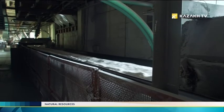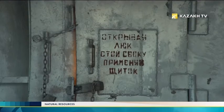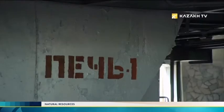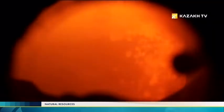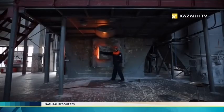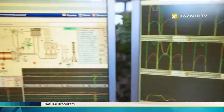The next stage is transportation and calcination of aluminum hydroxide. The final stage of all technological schemes of alumina production is calcination. Its aim is to transfer input aluminum hydroxide into ready-to-go product, which is metallurgical alumina for electrolytic production of aluminum, and non-metallurgical alumina used in different industries, including electrical engineering and ceramics production.